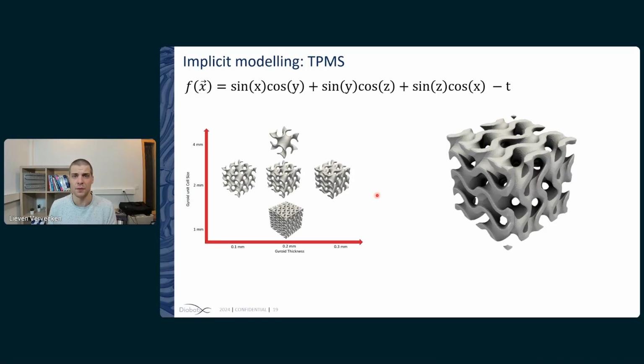This is basically a repetition of what I explained earlier. The gyroid shape easily fits within the unit cell approach. So you can easily, on one hand, change the unit cell size. If you have a very small unit cell, you can generate quite a dense structure, while if your unit cell is quite large, your lattice structures are not as dense. And within the unit cell, of course, you can then change the thickness of the structures. It's basically a thicken operation on your implicit function.